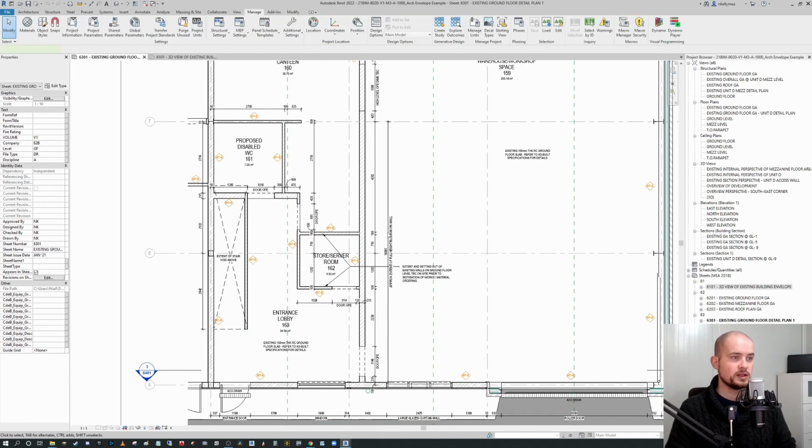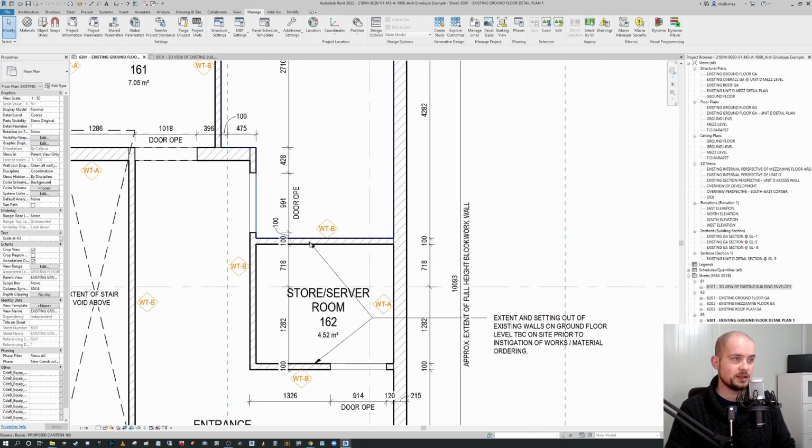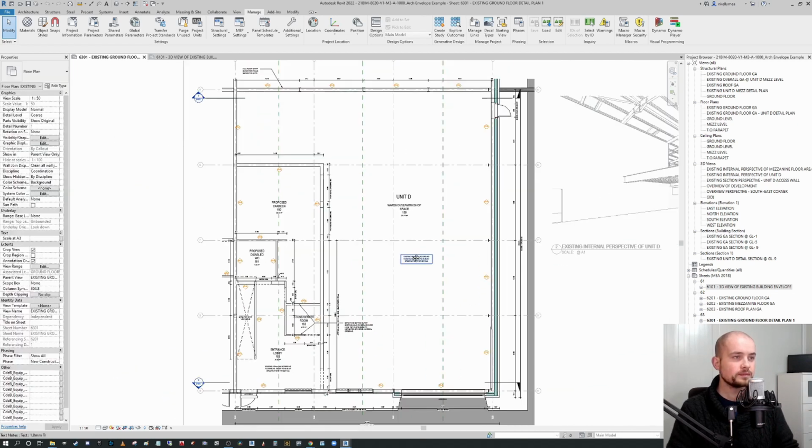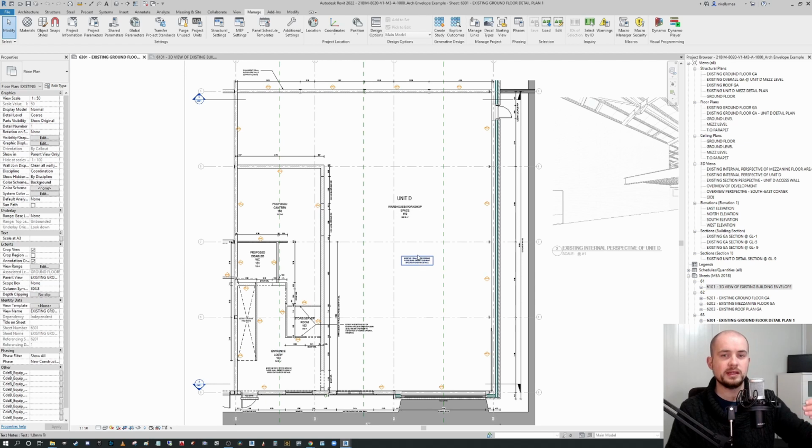You can see that these tags are not readily selectable because they belong to the host. In the architectural model itself, they are tagged linked elements. So we're not seeing the tags belonging to the link itself. We are seeing the tags that we put into the host model that are referencing the linked file. In historic Revit versions, if you unlinked this model at any given point, you would lose the association of these tags.